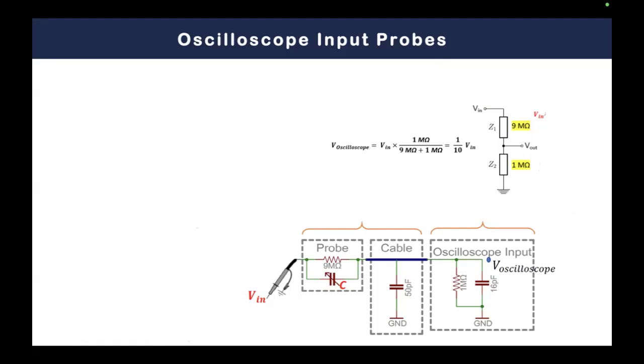If you go to the 10x mode, that means that I will get this signal as it is, and in this case I'm only showing 1/10 of the signal. And maybe one of the questions you can think about is why we have this 10x mode. Usually it makes more sense to multiply the signal by 10 to restore the 1/10 attenuation factor. But why should I make it in this way?